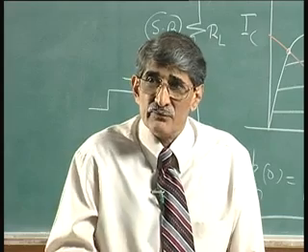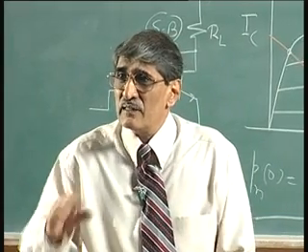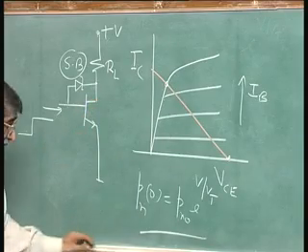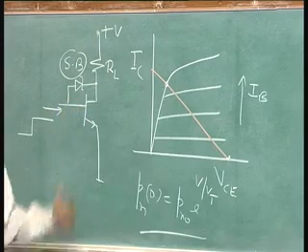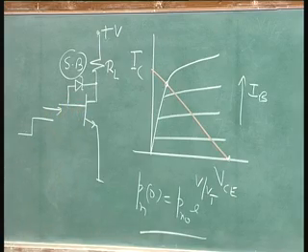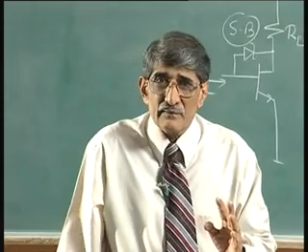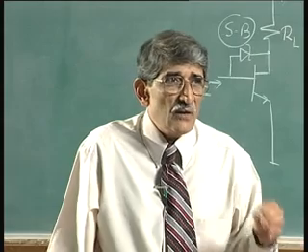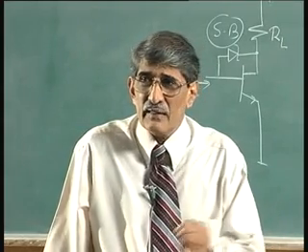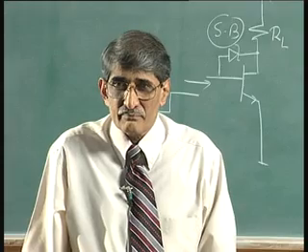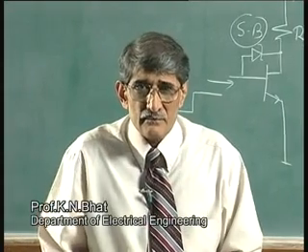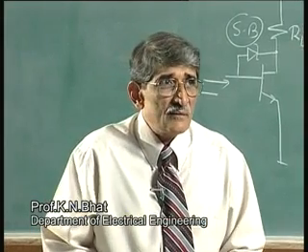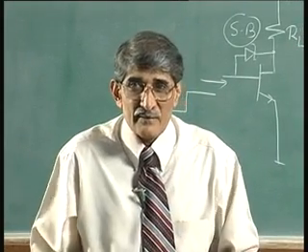So, high speed devices are made in silicon with a Schottky barrier connected across the collector base junction, integrated with that. Maybe later on we may have time to recall, but this is the key to the thing. That is one point. Number 2 that I want to discuss is why that difference between J naught between the PN junction and the metal semiconductor contact. You do not see this explicitly discussed, but if you very closely examine the mechanism of current transport, you can easily figure out what is happening.